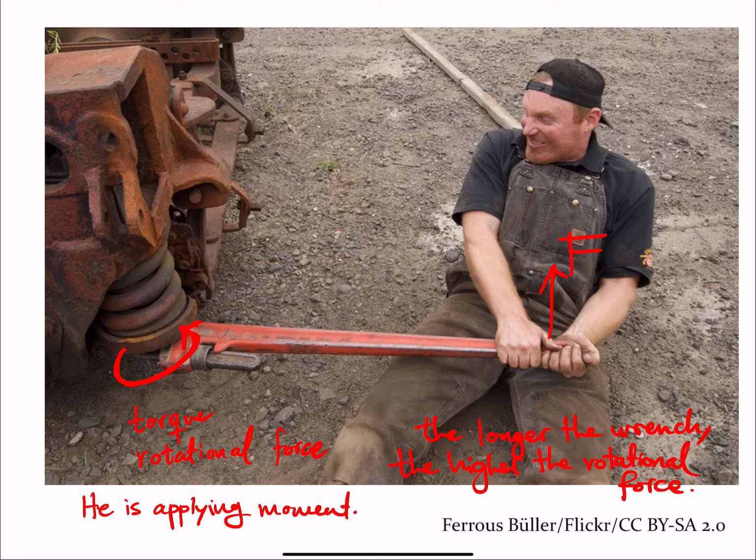So the rotational force is proportional to F, and it's also proportional to D, the distance or that length of the wrench. And that rotational force is what we call moment. So moment is proportional to force and distance.